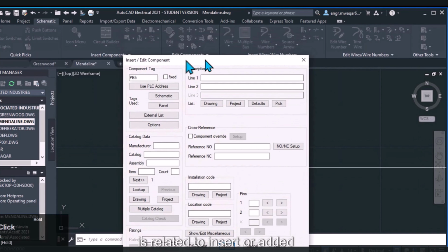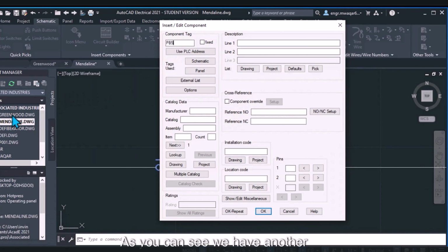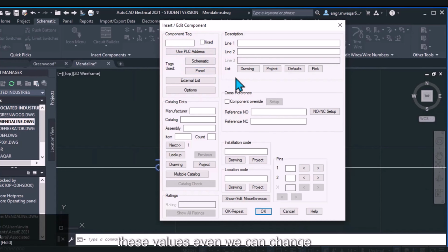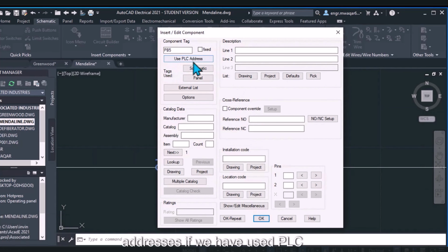So the very first push button you place on the canvas becomes PB1. The next one is PB2. But the automation here doesn't just look at the single page you currently have open, which is the crazy part. Oh no, it sweeps the entire project registry. Right, and that is critical when you remember that modern industrial blueprints aren't just one page. No, they can be hundreds of pages long. Hundreds of pages spread across dozens of distinct file directories.